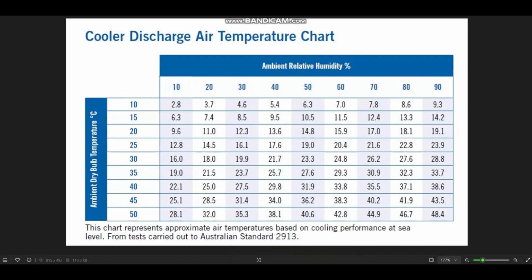What we now need to consider is the losses in cooling. If you have a roof-mounted cooler and just a straight steel dropper straight down to a plenum on the bottom, your increase in temperature will be very little, 0.2, 0.4 degrees Celsius. If, however, you have a flexible ducted network running throughout a ceiling cavity, as we find in your typical home, there might be significant more heat pickup.